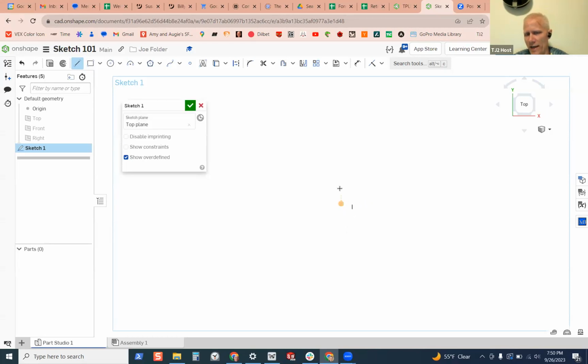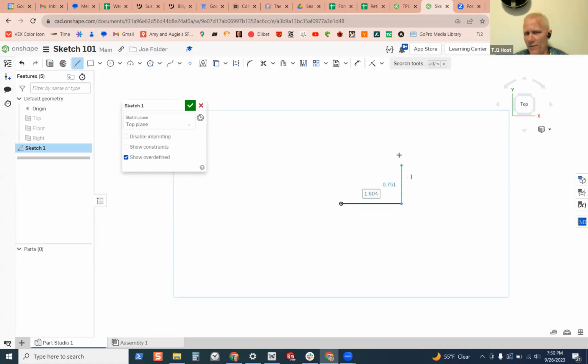So it's telling you, not only does it give you a pre-select, but it tells you what I'm assuming if you click now. So I want it to be incident. I'm going to draw a thing over here, a normal square. Okay. And then I'll draw inside, and as soon as I make a complete area inside, it fills it in gray.